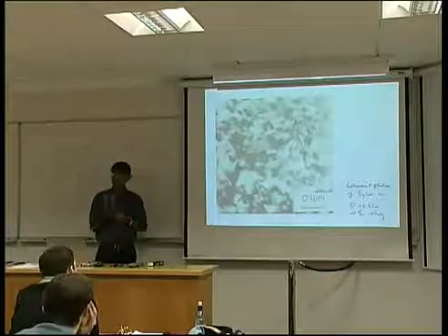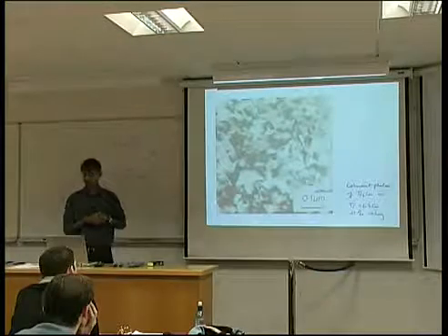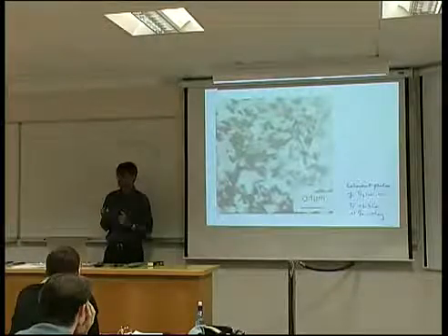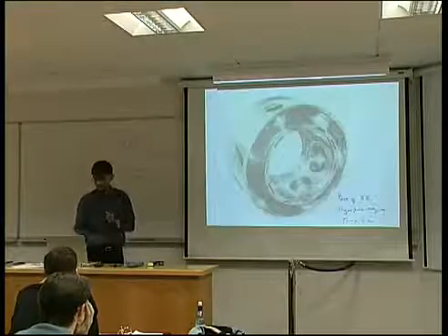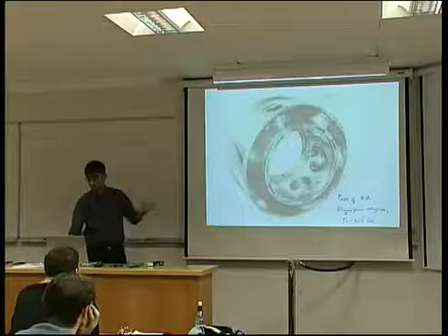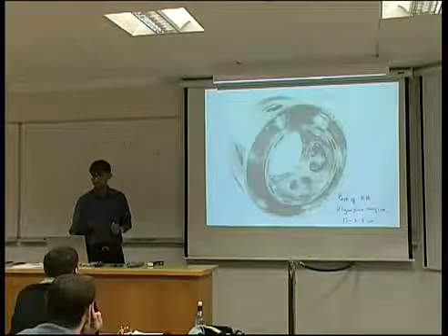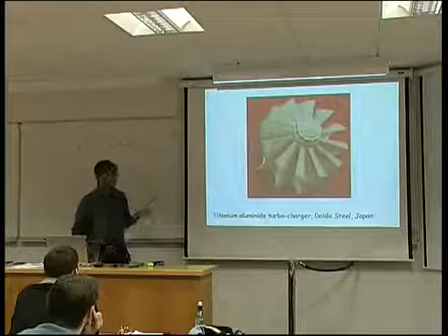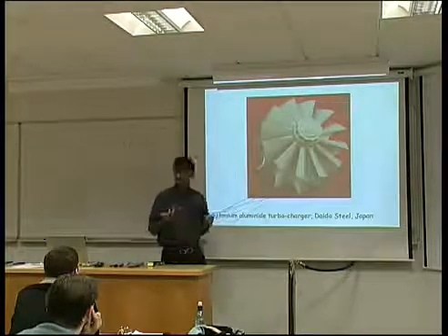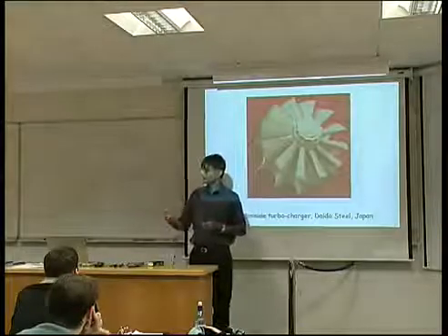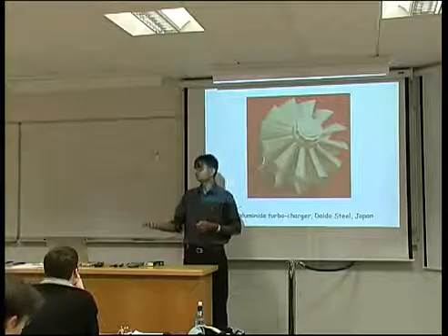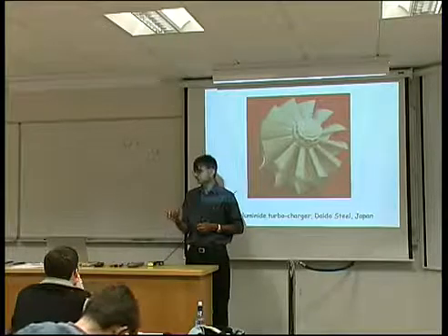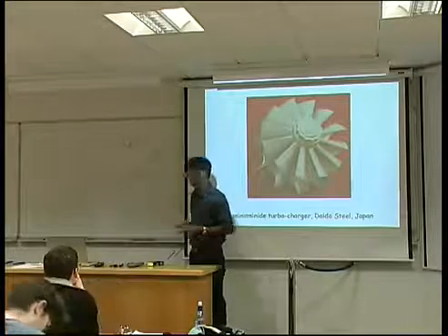Now finally, a few years ago there was a huge interest in making intermetallic compounds with titanium. So for example, okay, this is just the titanium copper precipitation hardened component. We can make titanium aluminides, TiAl or TiAl3, and of course they have the big advantage of low density and oxidation resistance.